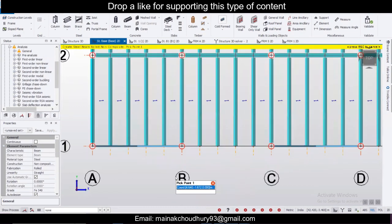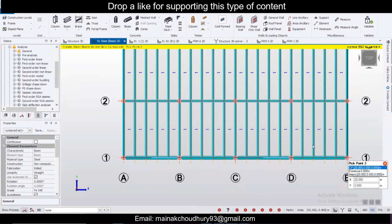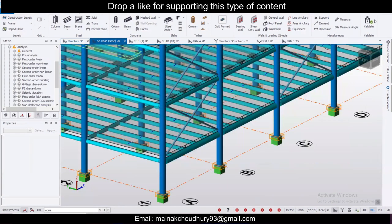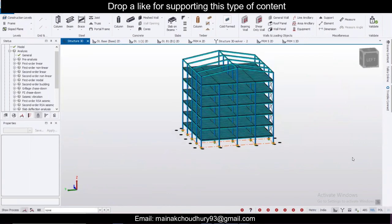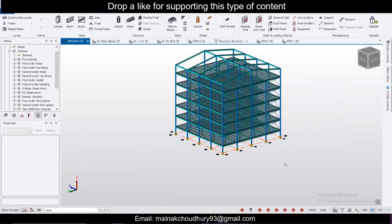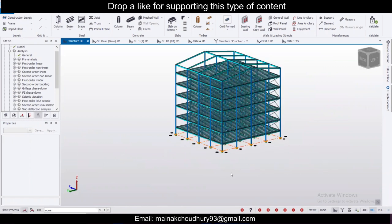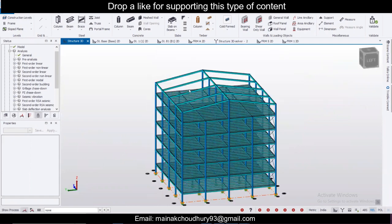This is the one, right? This is the one which you don't have. Go to structure 3D, validate. Now it's okay. So since I have inserted multiple times the bracings, normal bracing here, that's why this error had occurred. Okay. So similarly, we can place the bracings in this direction as well. So depending upon where is the opening and all, so you can do that.